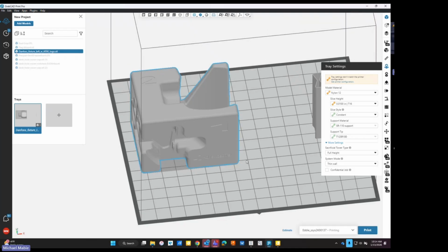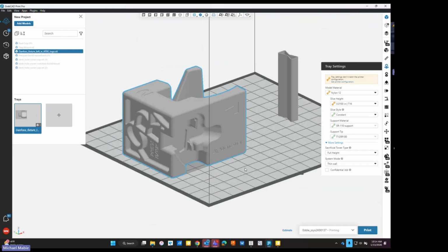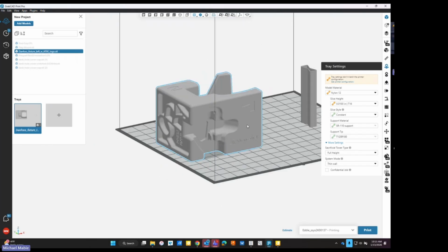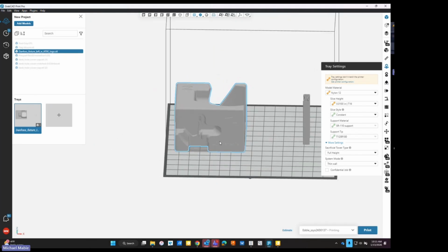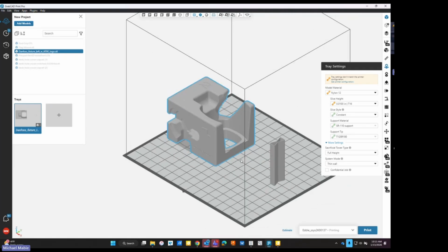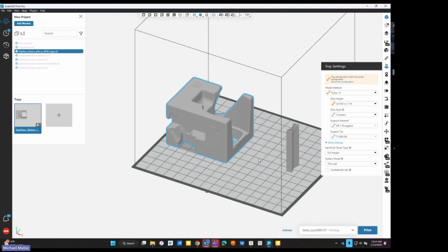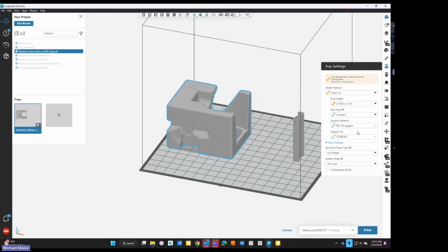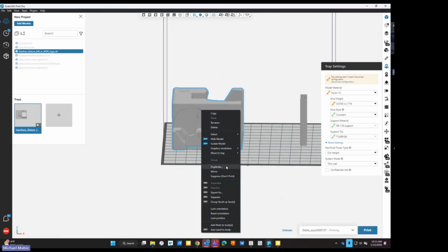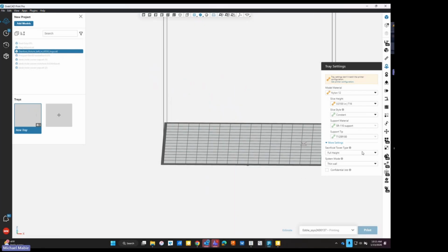If you run it at normal, you could counteract that by adding a wall stabilizer, which is going to help lock that in place and keep it from sinking or distorting. But that's where it gets to be a little bit of a mind confusion as far as the sparse versus your wall thickness, whether I'm talking about the full geometry or about changing it to sparse. All right, so that is one example. Let me go ahead and hide this one. Go back to normal.